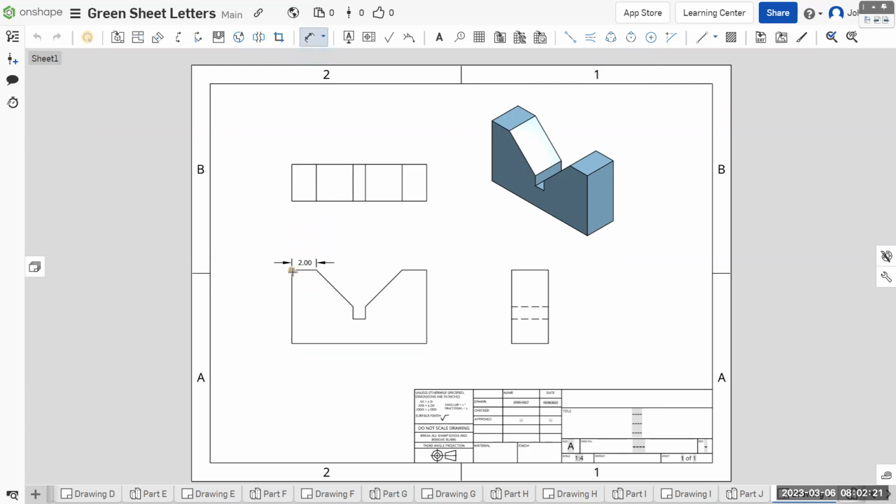Dimension tool, start on the left. The next thing that happens is where this edge happens. And back, the next thing that happens is where this edge happens. And these are long extension lines, but it is nice to go to that contour where on the top view, you're just going to these flat lines. It's not giving you any information. And dimension the other way to the other side.